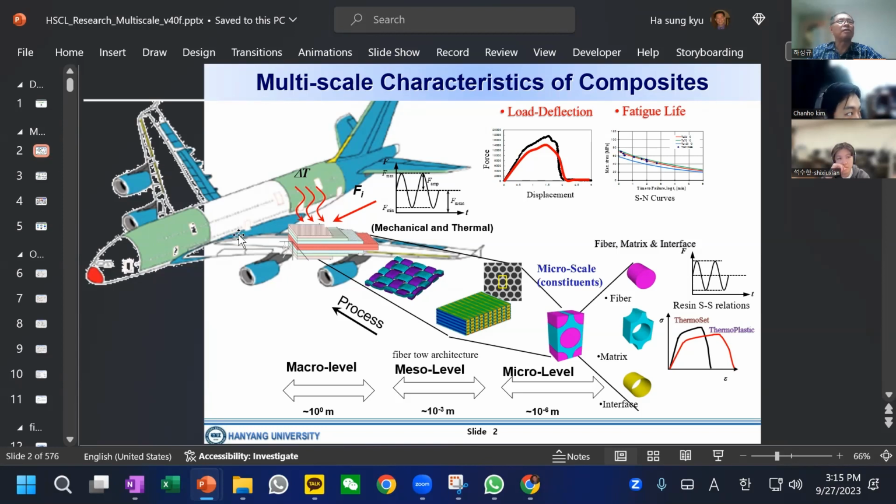So in composite material, the design covers the shape of the outside, but inside we have layups, which we, the designers, decide. With a conventional metal, design mostly means the outer shape and thickness, but for composites, not only the geometric outer shape but also the layup sequence, which makes for different material properties. So with composite material, we create the outer shape, but also we create our own material property. That is the beauty of the composite material.